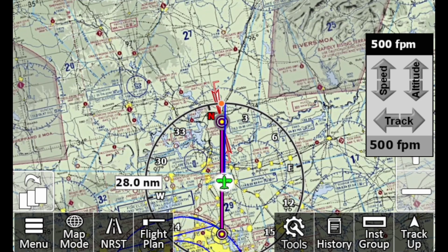So how does this actually work? iFly sends standard NMEA data, which includes things such as your altitude, speed, and flight plan to your autopilot. Then your autopilot is going to read this information and adjust your aircraft to follow your programmed route. Now we can jump into each connection option and the specific settings that you will need enabled in iFly.